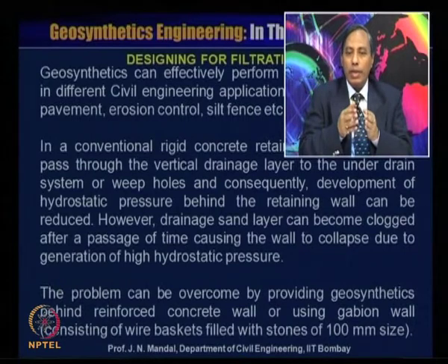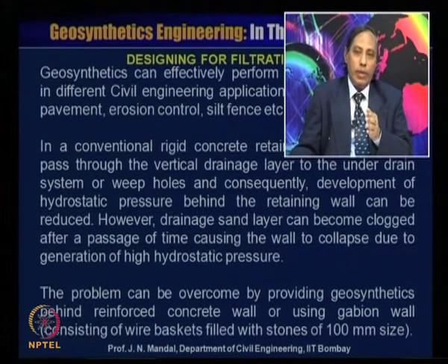However, the drainage sand layer can become clogged after a passage of time, causing the wall to collapse due to the generation of high hydrostatic pressure. The problem can be overcome by providing geosynthetics behind the reinforced concrete wall or using a gabion wall consisting of wire baskets filled with stone of 100 millimeter size.